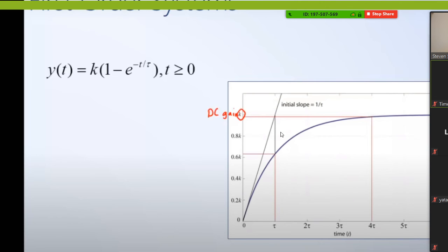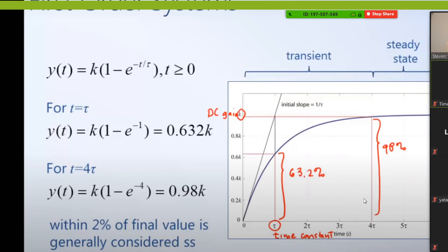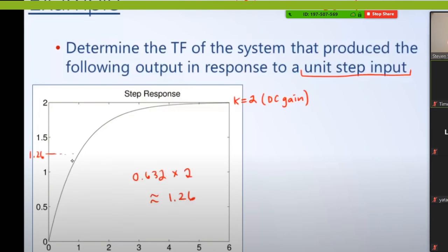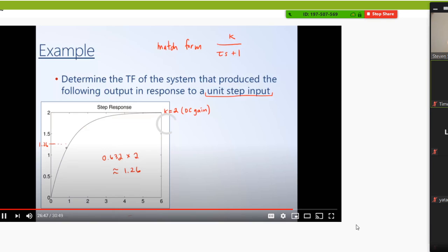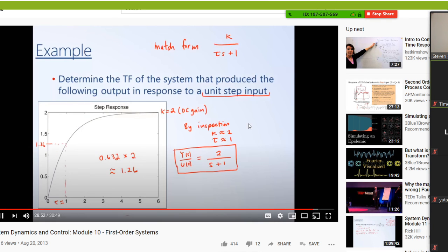And then the static gain again. An input, which in this case is a step. So this is the steady state gain, how much the output will be multiplied. K is the gain. The output only approaches the final value. I hope that, being given the output response and time, you can try to back out the model. And actually for this project, you only need to use a first order model.